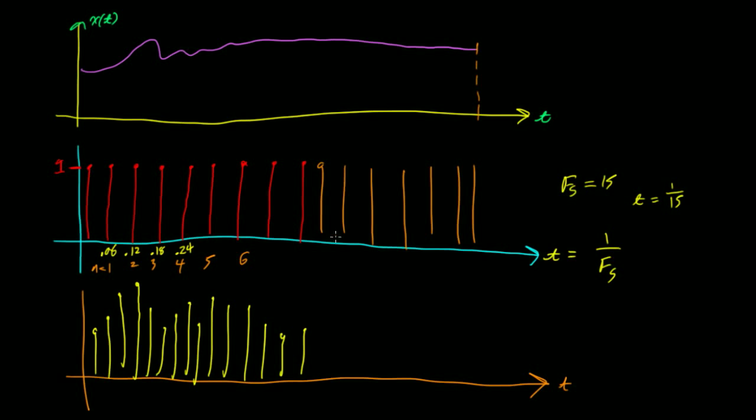But the point is, as I'm increasing my sampling frequency, you can see that I'm getting closer and closer to my original signal. Right now, I've hit almost just about 20 hertz for my sampling frequency, which is right at the Nyquist frequency. That satisfies that the sampling frequency has to be double the frequency of the cosine.